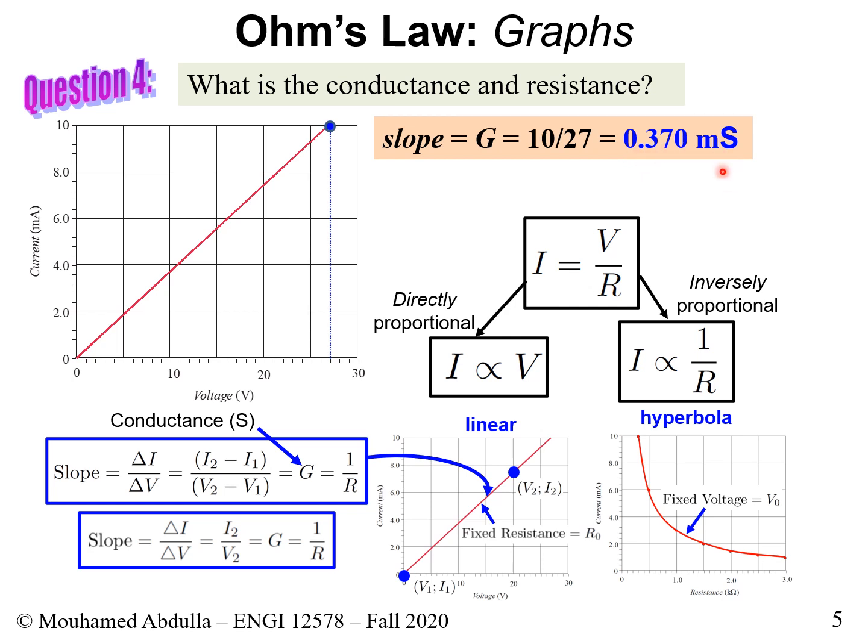Now you might say, where did the milli come from? It came from here, because this shows in milli, and therefore you have to bring it here. You have to put milli in here, and this is millisiemens. So this is a conductance. So we basically answered this question. What is the conductance of this circuit? Well, from the graph we determined the slope, and the slope gave us the conductance.